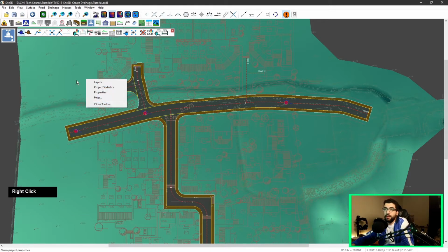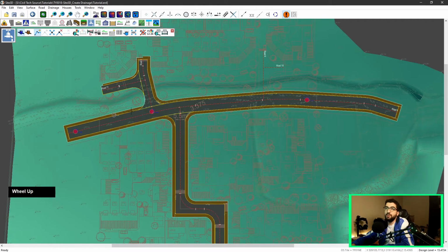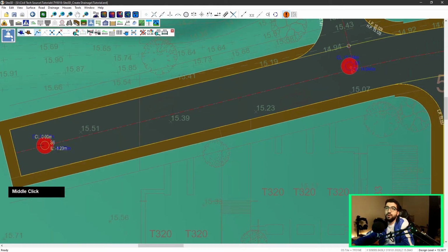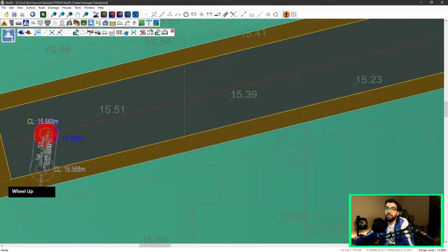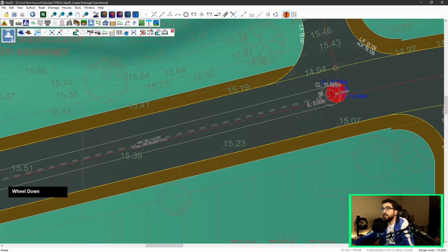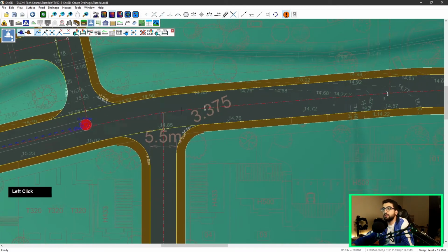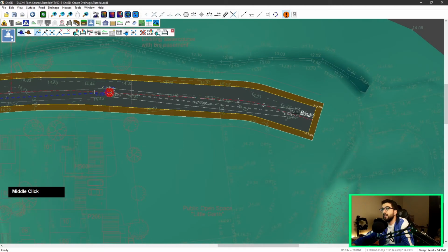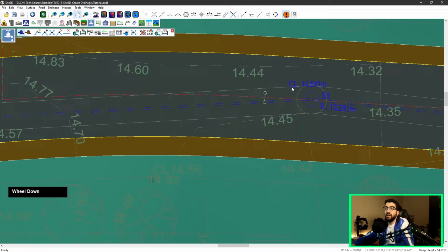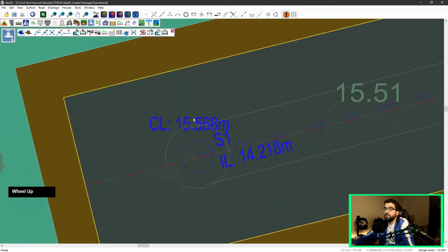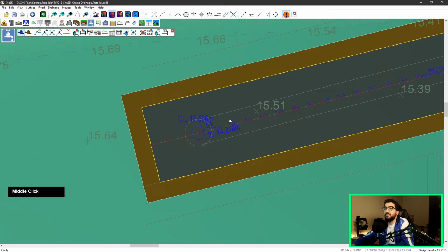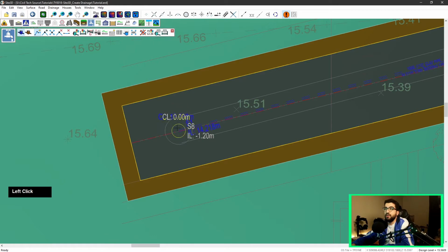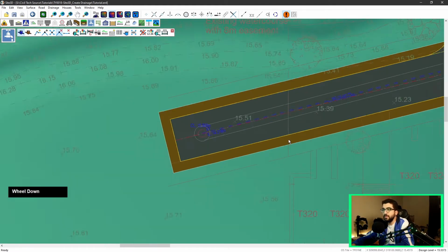Now let's go through adding a new drainage run. So let's say we want to connect these two pipes. All we have to do is go close, select it, it will automatically pick it up, and then we draw again and again and boom, and quit command. And as you can see here, it doesn't draw duplicates. It realizes that, yeah, there is a manhole there. So if I drainage run, you automatically see it highlights it. If I put one next to it, it will automatically become red. So we have to delete it. But other than that, yeah.